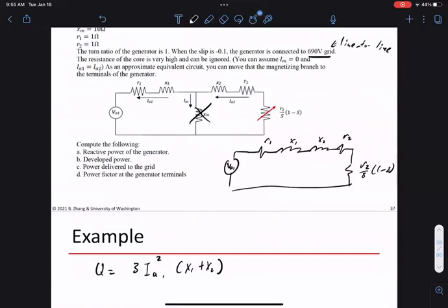When you see this kind of voltage given without saying what it is, it's always line-to-line. To convert it to the per phase voltage, this is 690 over root 3. So this root 3 comes back again into our equations, because you will still be doing line-to-line and per phase conversion in this.